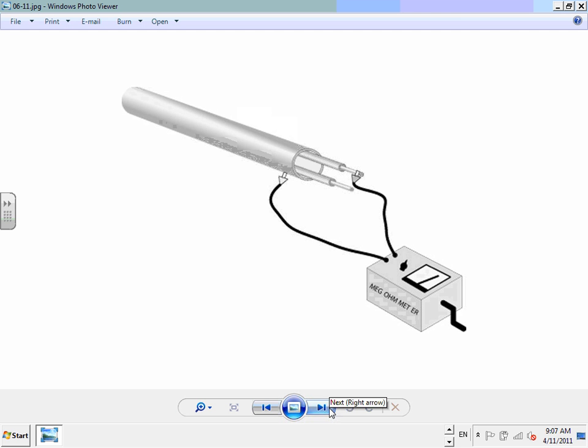Mr. Rubeb, we as electrical engineers, we care about THHN conductor. But you send somebody like DJ, half a banana electrician, to pull all these 500 kcmil conductors in a conduit, and he's so mad at his boss. While you're pulling it, you cut half of the insulation of this THHN. Now what happened to you? You compromise the integrity of this 40 to 50 year old cable. That's supposed to be a 40 to 50 year old cable. You damage it, you compromise the insulation.